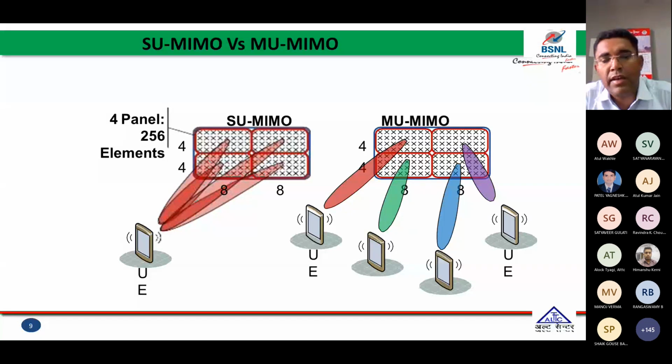In 4G as well as 5G, in the uplink direction, maximum only 4x4 layers are there. Why? Because with 4 layers on the UE side, all the antennas are installed in a very small area. That's why all the antennas are very close, and the wireless propagation channel paths are highly correlated. That's why more than 4x4 or 8x8 is not feasible in that case.